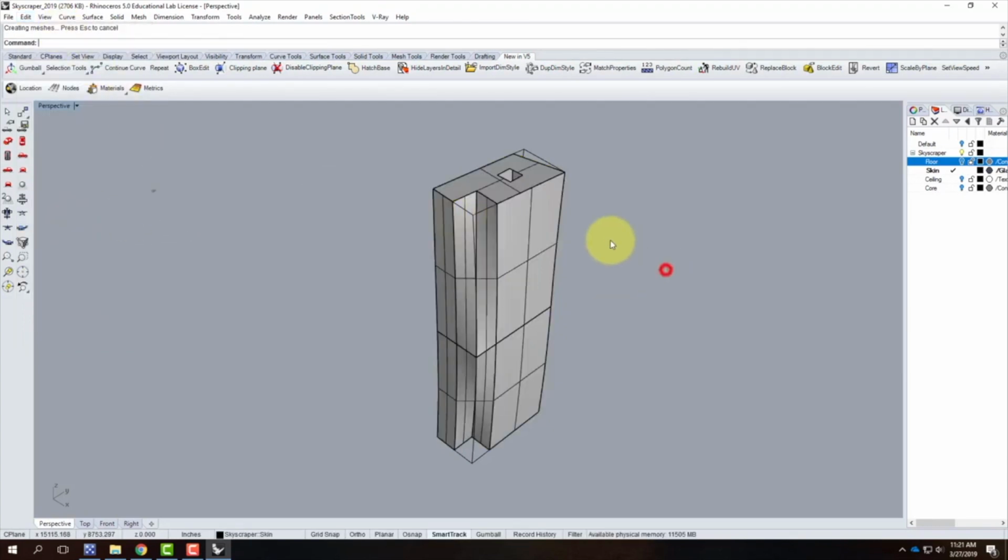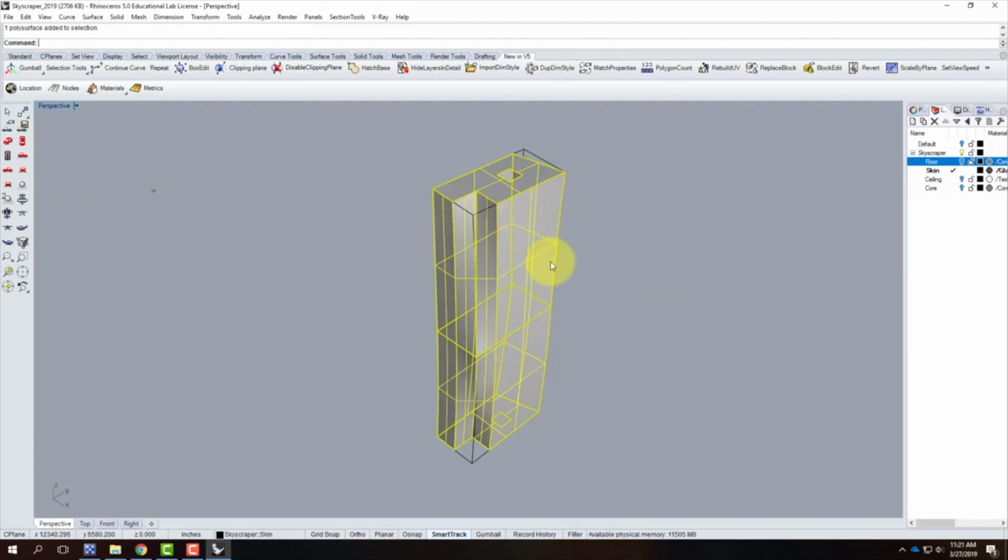And it's going to join these individual surfaces into one polysurface. It's important when we do the unrolls to join it into a polysurface because edges are going to match up. If we unroll, we could unroll each surface individually, but you'd have to manually figure out which surface matches with which surface. And that's a lot harder than making it a polysurface first. So it's a closed polysurface, and it's now time to start the unroll command and basically flatten out the pieces.